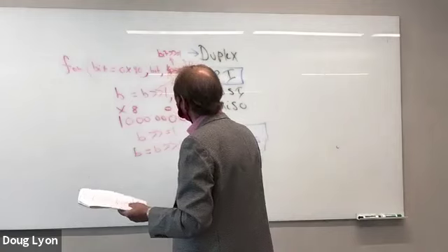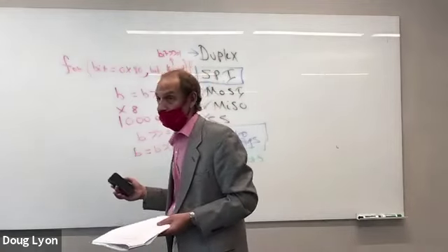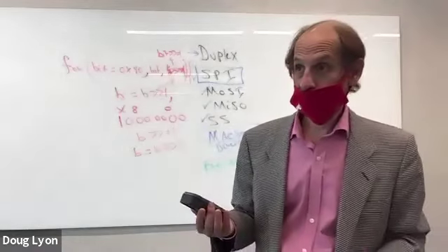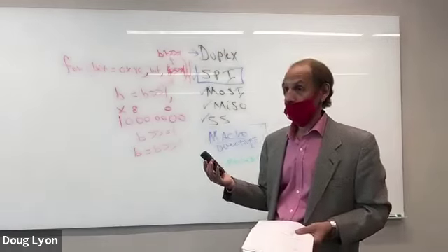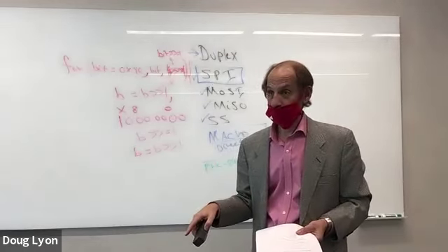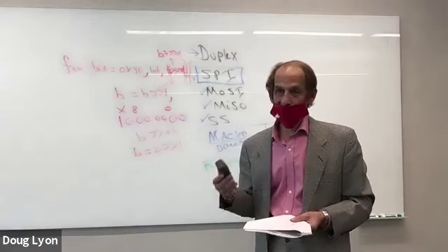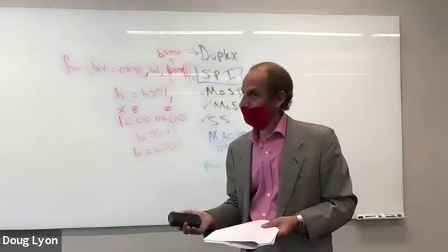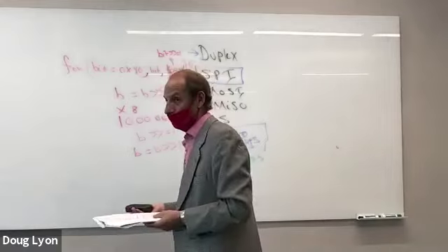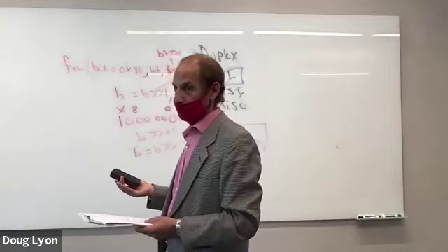Right? Because what you're really trying to do with the bit flipping is get deep into the understanding of the hardware. Let me tell you something. When I did this sort of thing for a living, I ended up poking my nose into the data book for all the chips that I was using. And I had to do the same thing for the Microchip DAC. If you don't read the data book, you're not going to know how to flip the bits and you're not going to get it to work. It's as simple as that. A lot of times there's no programmer guide, there's a data book. Read the data sheet on the device, and then you can learn how to program it.